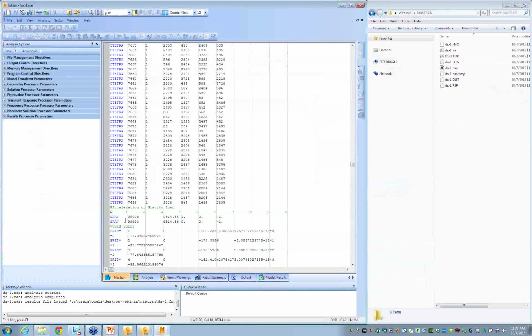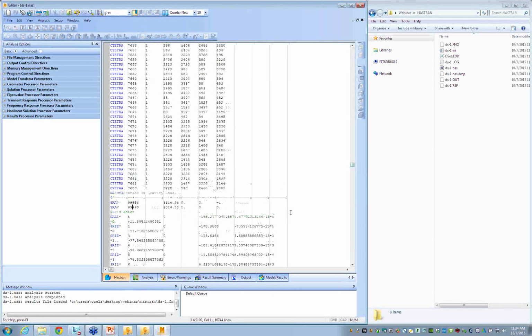So we have a new gravity, and this time I wanted that new gravity to be, let's say, 0 in the Z direction, but plus 5 in the X direction. So I just changed not only the direction, but the multiplier as well in a different system. To make things simpler, I'll just put it in the X direction as a plus X. Okay? So now I have 2 gravity multipliers. I'm sorry, I have 2 gravities defined. I just have to add them into the load definition.